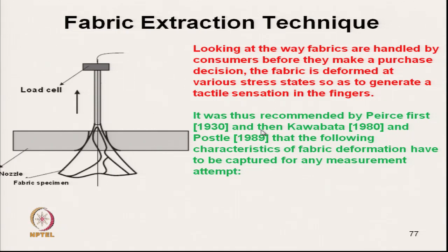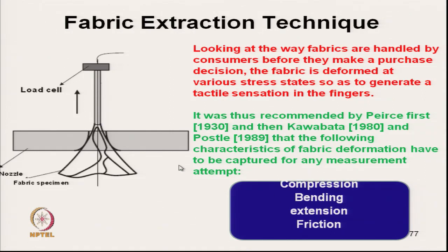It was first used by Pierce, then Kawabata and Postle, different groups who have attempted to measure the extraction force and correlate it with the fabric handle characteristics. During this extraction the fabric is undergoing compression, bending, extension, friction, all these forces coming into play.